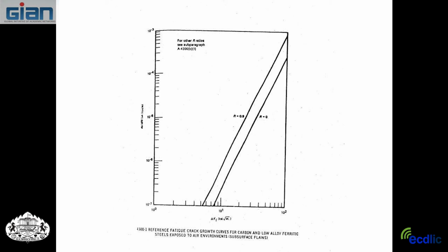One of the bad things about these is that the abscissa here, the horizontal ordinate, is a temperature that is not based on fracture mechanics, but based on NDT. I don't know if any of you ever tried NDT testing. What they do in NDT testing is have a specimen with a weld defect, and they have a huge machine with a weight high up in the air, and they drop it down, and it comes down and whacks the poor specimen, and then they see if the specimen cracked or not.